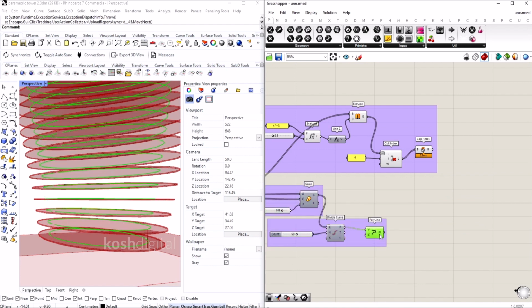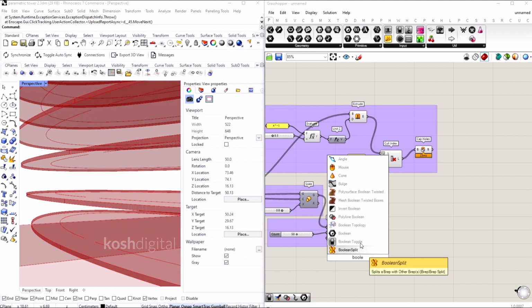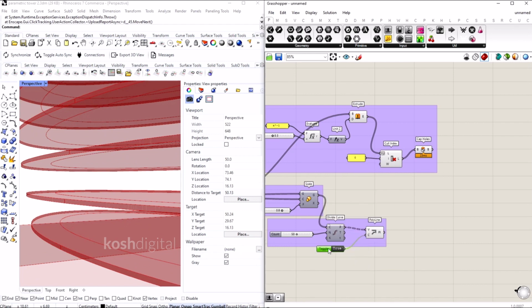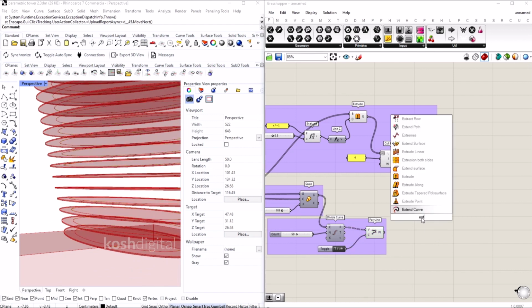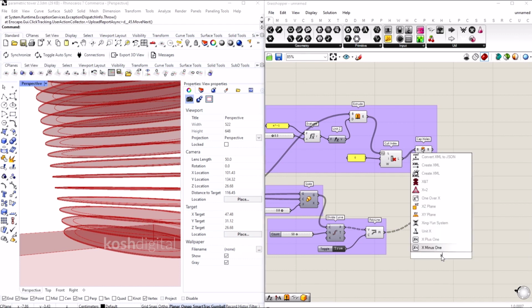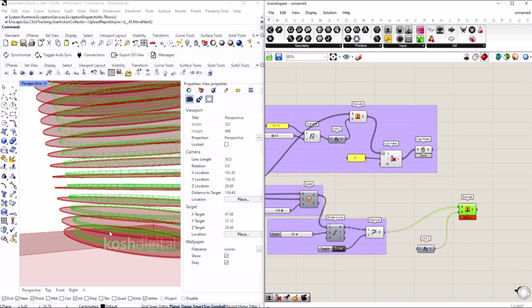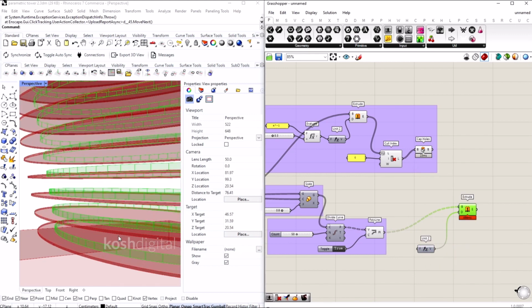Switch it off. Now if you look at it, it is not a closed curve, so we just have to give a boolean toggle as true, connect it. Now it's connected. Now let's extrude this curve, polyline, okay, to a z value. So z vector, connect this here. So by default it has 1 unit.